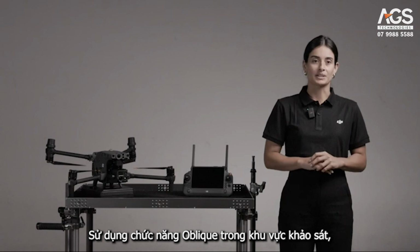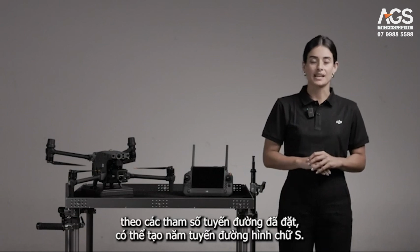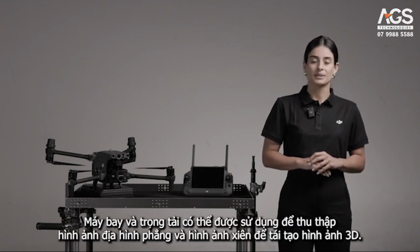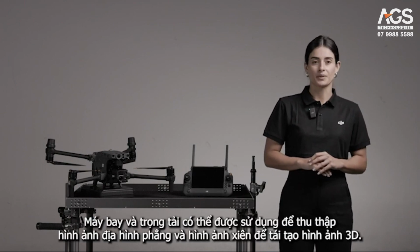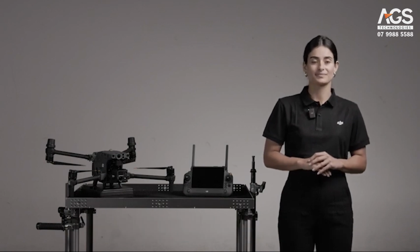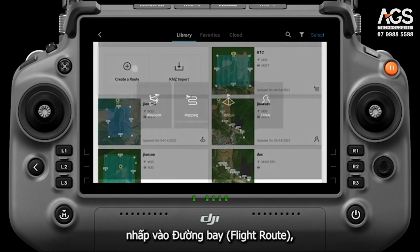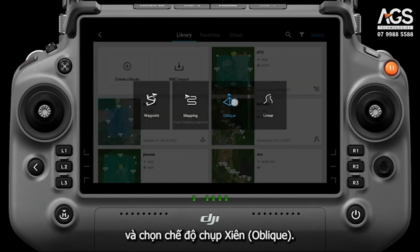Using the oblique function in the planning area, according to the set route parameters, 5 S-shaped routes can be generated. The aircraft and the payload can be used to collect orthophoto and oblique images for 3D reconstructions. On the home page of DJI Pilot, click Flight Route, create a route, and select Oblique.